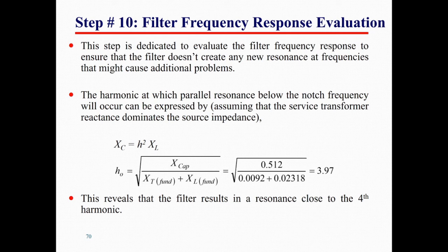Filter frequency response evaluation. This step is dedicated to evaluate the filter frequency response to ensure that the filter does not create any new resonance at a frequency that may cause additional problems. So now we need to check how the impedance of the filter changes with the frequency.